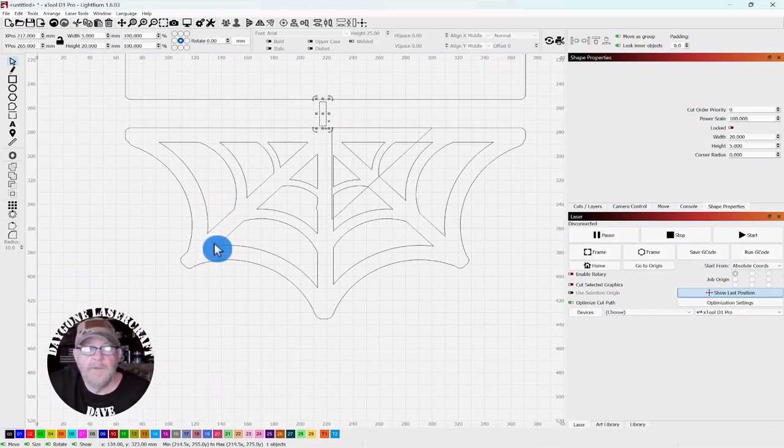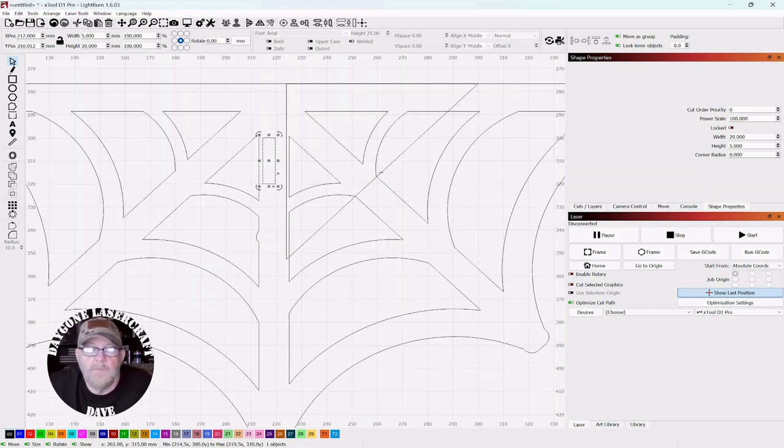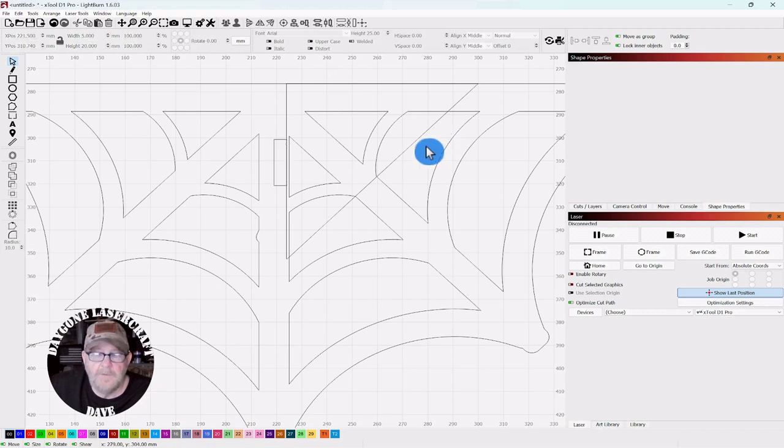So select, use the period key to rotate clockwise. You can use the arrow keys to move it into place, but what we really want to do is get on the edge, grab with your mouse, hold the Alt key, and snap it to our brace like that. And then we will get to a place that you can clearly see the brace since we've got it laying on top of the other stuff. And then with your tab selected, shift, select your brace, and then you can go to horizontal center and move that to where it needs to be.